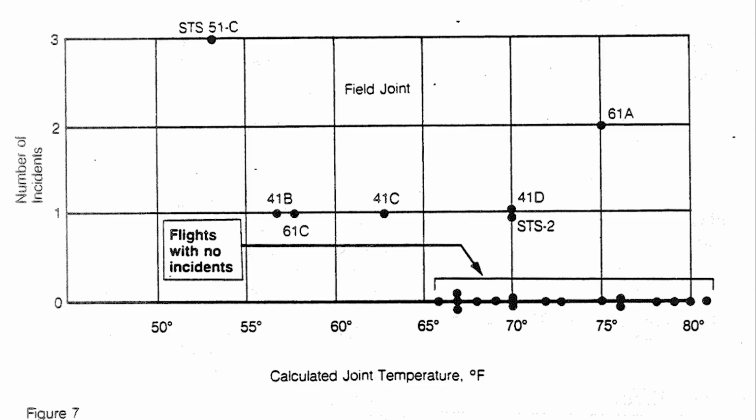So the best example you can take on how to better present your data is shown in the next slide, which basically in the next table shows you the data not just of the flights where there was an O-ring failure, but also includes the flights where there were no O-ring failures. And so what that starts to show you is that, as the temperature goes up, there are fewer and fewer. Of the launches that had failures, anything below 65 degrees had some problem, right? Anything above 65 degrees, there was an occasional problem, but it got less.